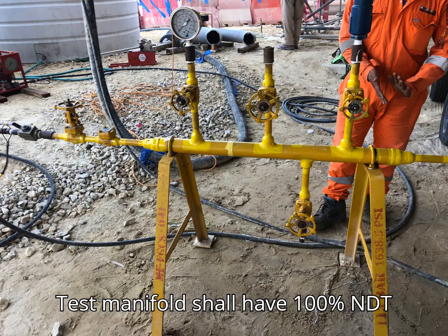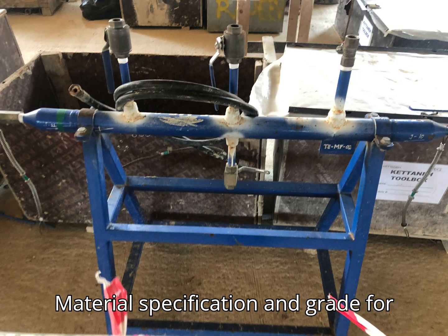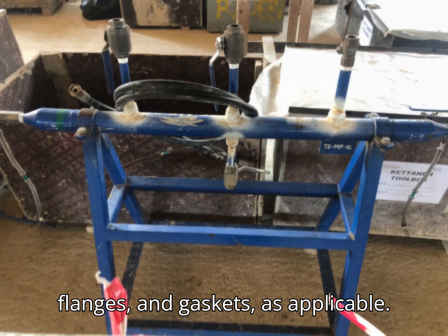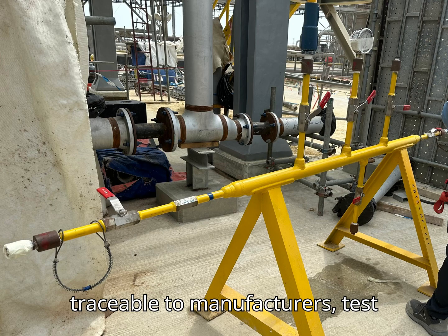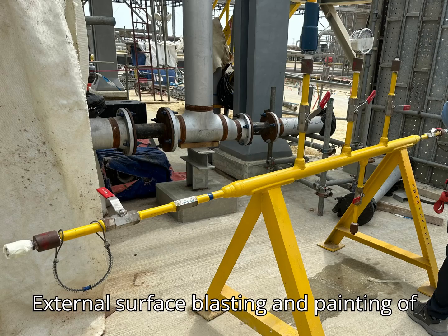The test manifold shall have 100% NDT of all welds. Material specification and grade for the structural, pipes, fittings, hoses, flanges and gaskets, as applicable. All materials used shall be traceable to the manufacturer's test certificates, or MTC. External surface blasting and painting of the manifold.